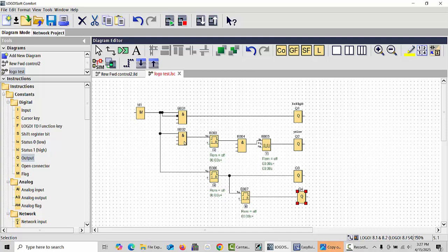After that, one thing to remember: this is the B2 block, your AND block. You have to make this one inverse, and this Q4 you can connect with this B2 AND block. Okay, and one line you have to connect with this logic line, and make this one inverse also, and make this line with the Q3. Okay, this looks like it, I hope.